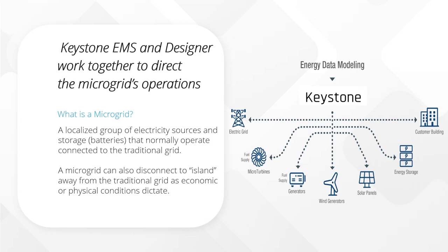Everything has to work together nicely. Everything has to play nicely together to make sure that you can disconnect yourself from the grid in the case of an emergency, and then black start. Come up from darkness, from no power to power, in a way that no two systems are fighting. By fighting, I mean if you try to turn on, let's say, a gas generator and something else that is trying to also produce power, and you do it in a way that is incompatible, they're both sort of grid forming, then there's going to be a problem. One of them is going to go back down.